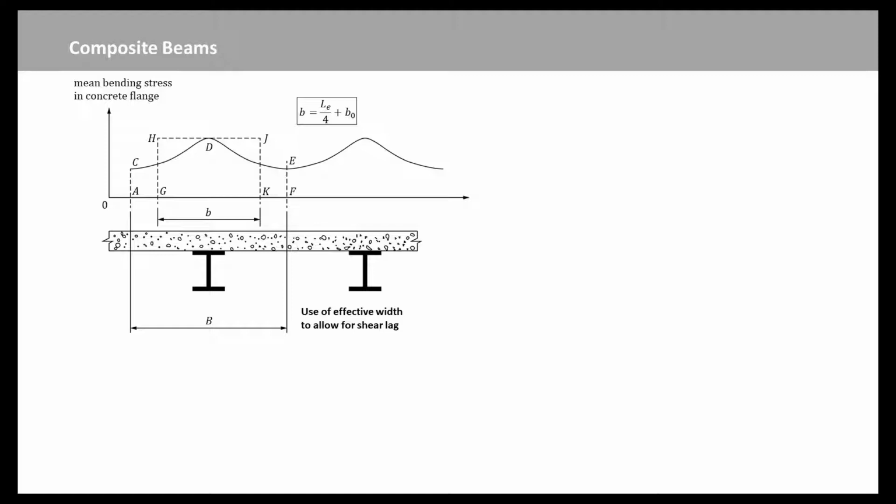Research based on elastic theory has shown that the ratio B_eff over B depends in a complex way on the ratio of B to the span L, the type of loading, the boundary conditions at the supports, and other variables. At a cross-section of maximum bending moment, the compressive force in the slab is usually independent of the effective width, being governed by the tension in the steel member.